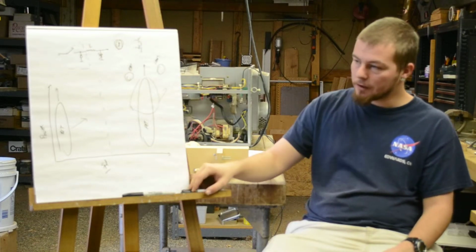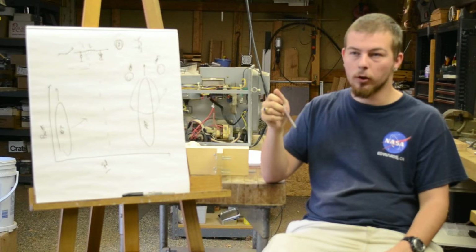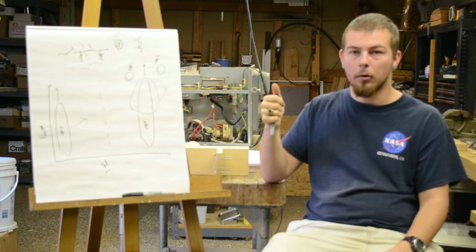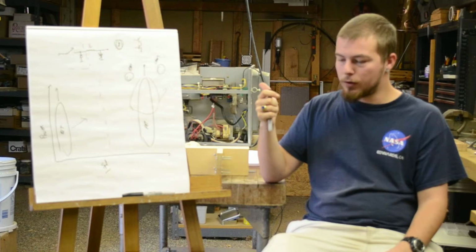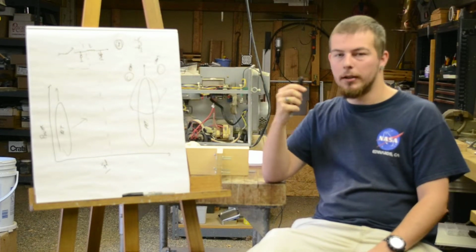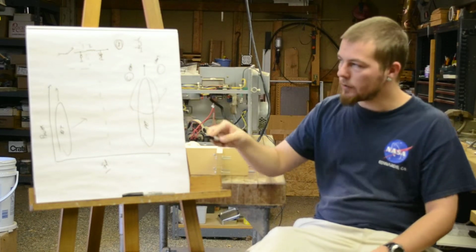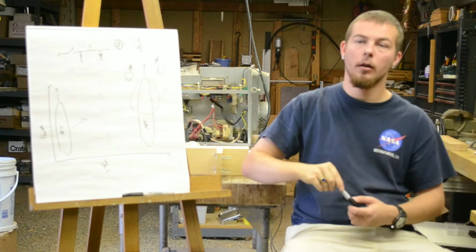No, that's not the case. Transformers are very much sized to their power level, and so to get a system capable of providing 12 volts at 100 amps, you would need a ridiculously large transformer. So that's where the switch mode stuff comes in.